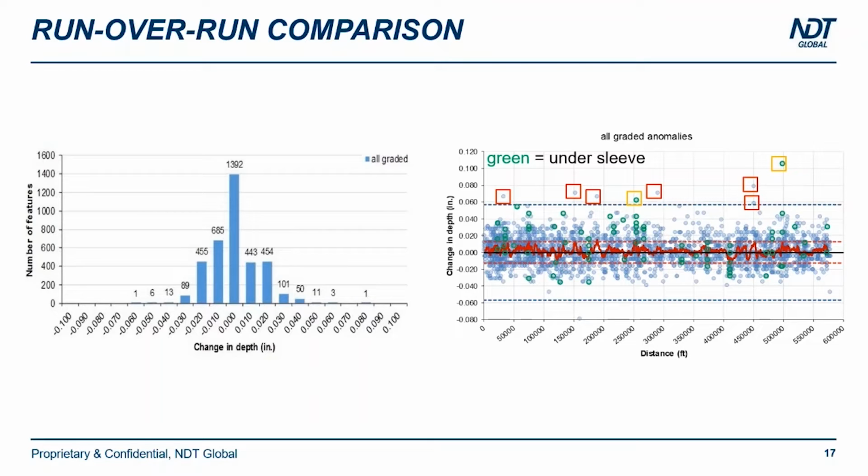We know that the robots have a specific tolerance, but what happens when we're compounding information? We have to take into consideration this statistical tolerance as well. So when we have something beyond that statistical tolerance, there is something being identified. In this particular chart, the green anomalies are things that are already repaired, considered stable. And in this particular case, we have 2 that have significantly shown change.